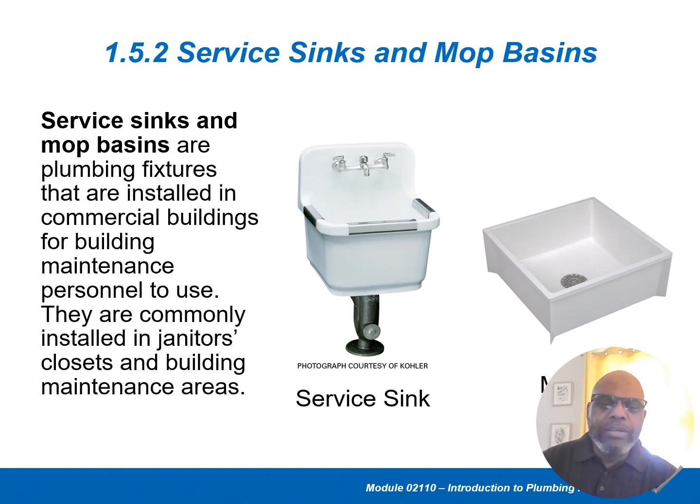Usually the drain in it is very large compared to a kitchen sink. The drain in these is going to be at least 2 inches in diameter. They also have a cleanout, so if it clogs up for any reason, you'll be able to clean it out. Again, a service sink is also used for washing out paint brushes and things.